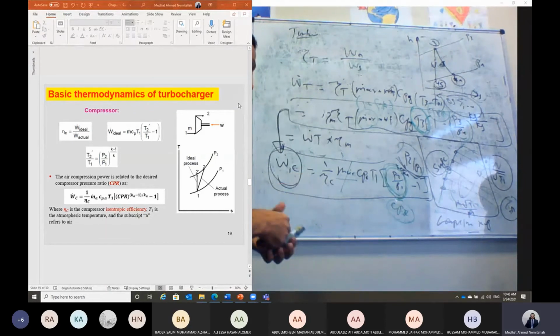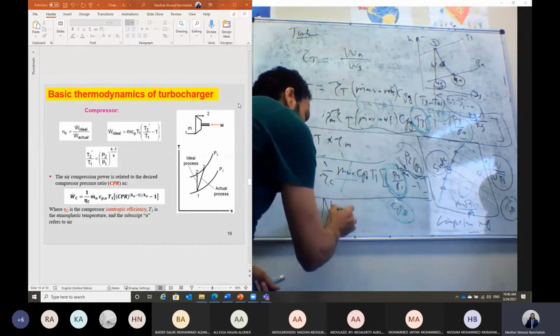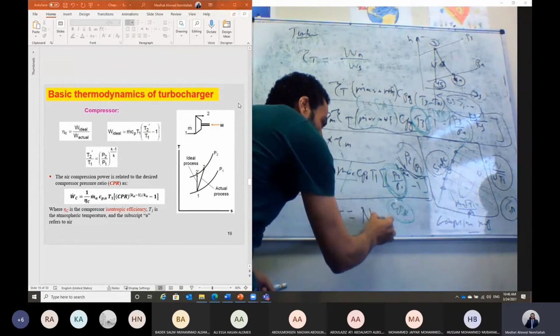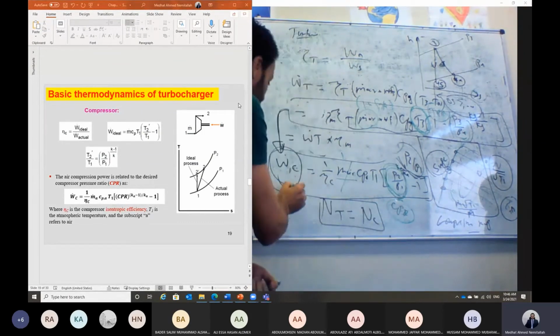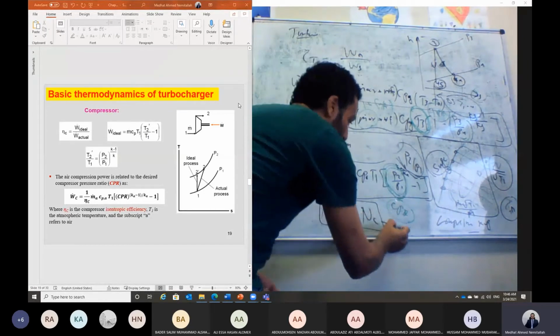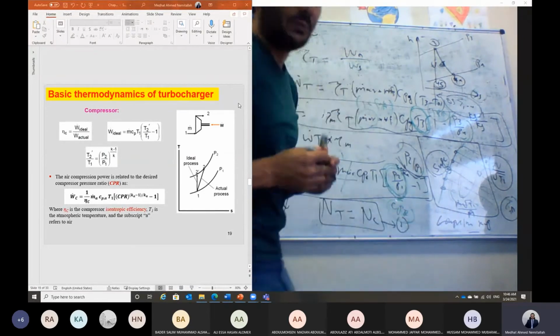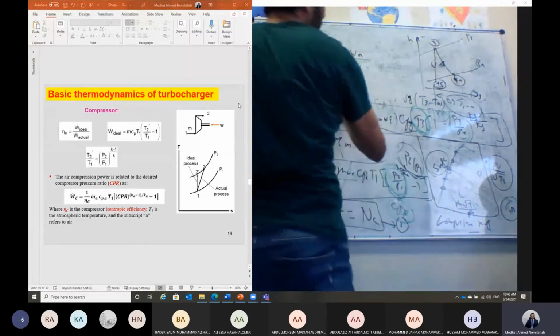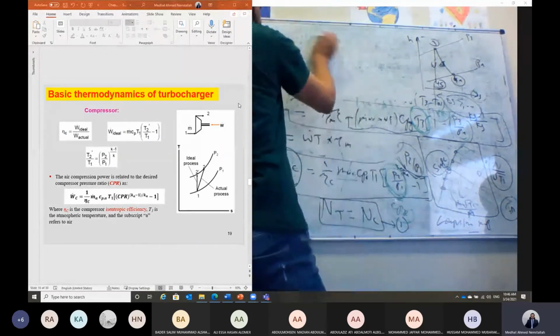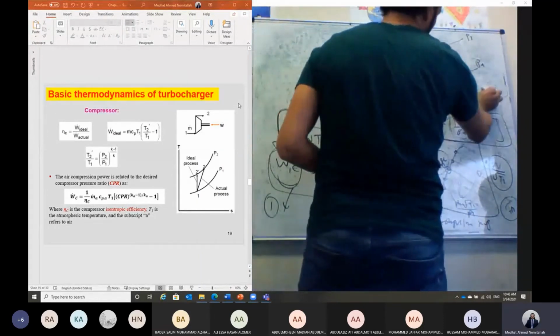And we have another equation for turbine and compressor, that the RPM of the turbine should equal the RPM of the compressor. Let's say this is equation number 1, and that should be equation number 2 in the matching process. Right? What about the engine itself? We said the engine will be deciding about what, Shabab? The engine will decide which of those parameters?